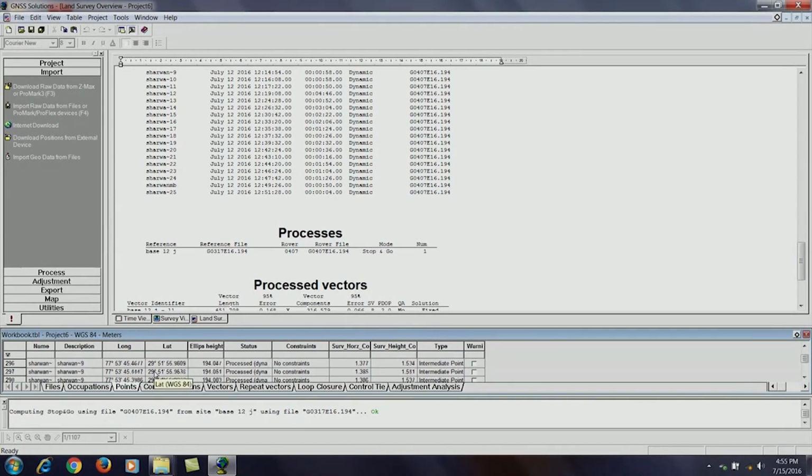You can see here that so many points, 360, 370, 399, 480, like that. So, 1071 points are there, and their coordinates, latitude, longitude and height are there. All these things we can take in an Excel sheet, and from there we can go to mapping software to plot these points, and joining these points we can get the corner of the road as well as the boundary of the field.